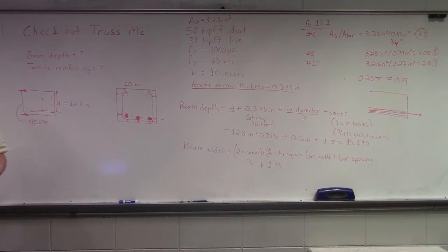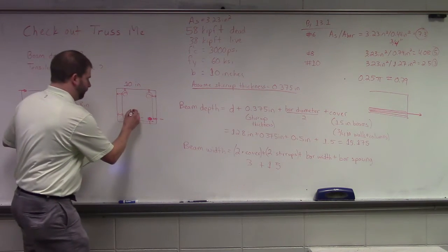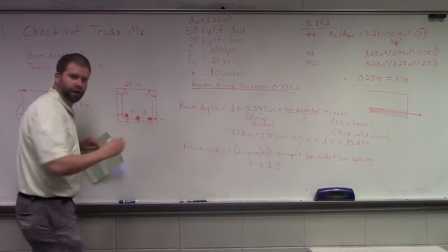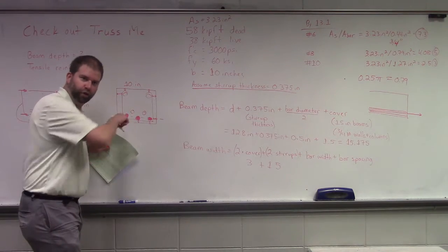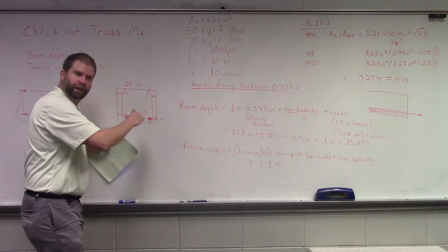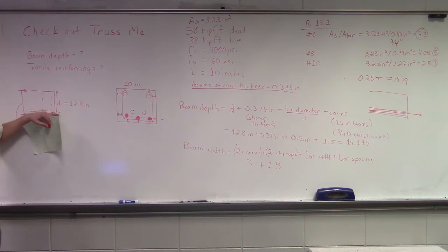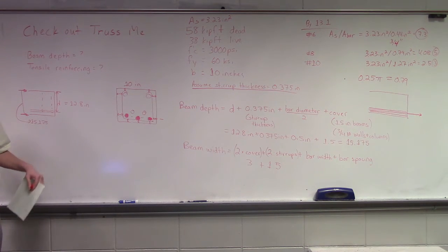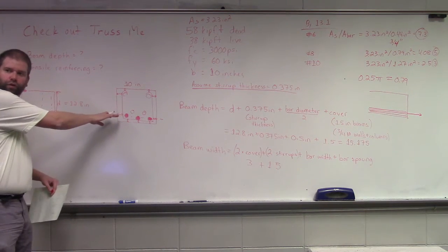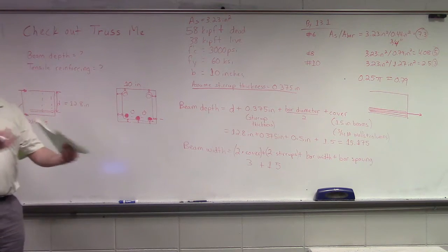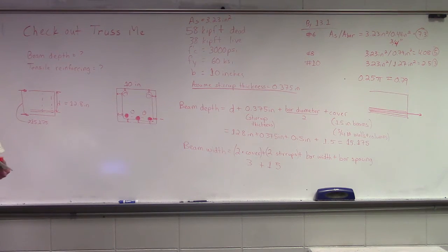It's going to depend on how we actually lay it out, right? If we lay it out like this, where we have 2 bars in the top layer and 3 in the bottom layer, the centroid won't be halfway in between them. It'll be closer to the layer where there's 3, because we're going to have more mass down there. So you take your mass and figure it out.